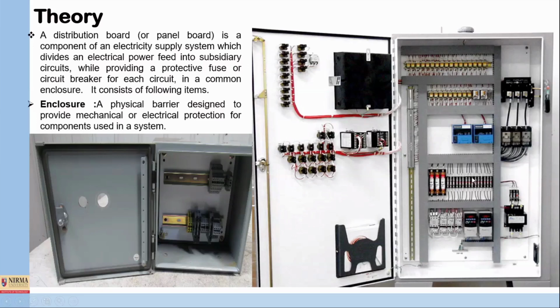It will sense the internal temperature, and when the temperature is more than normal, it will switch on the fan, and this fan will blow out all the hot air from this chamber, and there will be cool ventilation from the outer side. Some holes are there, so outer air will come inside. I mean, cool air will flow inside, and hot air will be exhausted by this particular blower. Okay, this fan, just like this fan.